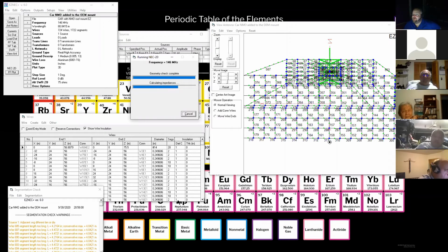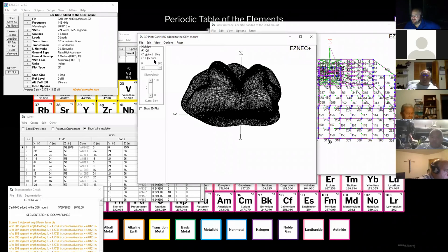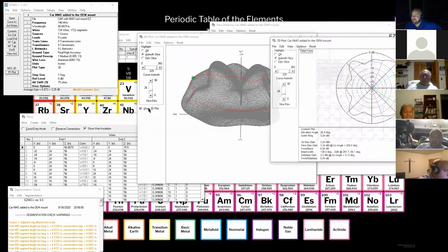again, the big takeaway about this is if you make big complex models, I've had antenna models in another program that can do much more than this one that I've literally had to let my computer run overnight, and I come back the next morning and I can look at the pattern. There's a lot of math running back here. A Raspberry Pi ain't going to keep up. So, okay, things are starting to look more realistic now. Oh, 3.25 dBi of gain. Still probably more than it's actually making, but more realistic. So these settings can make a big difference here.